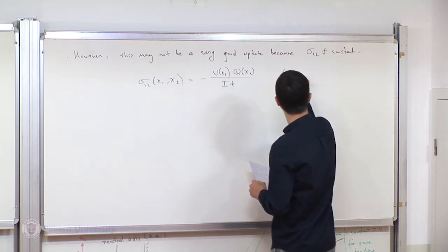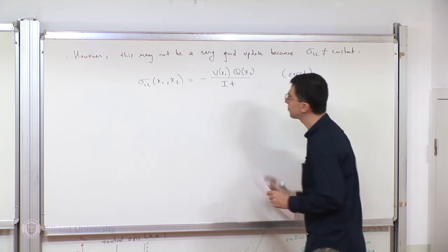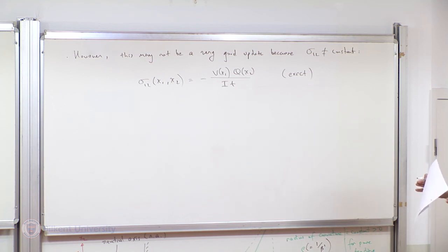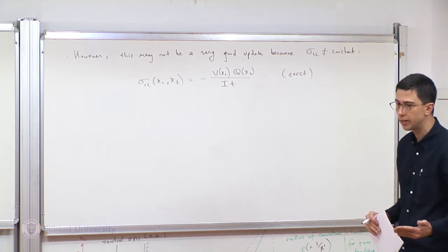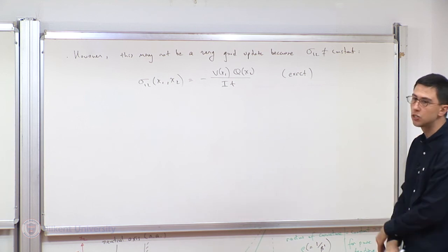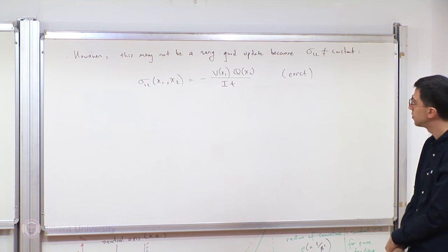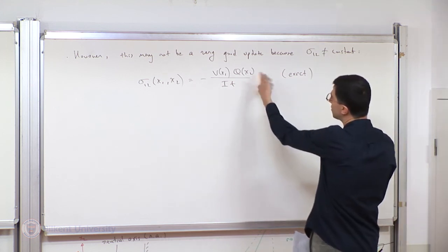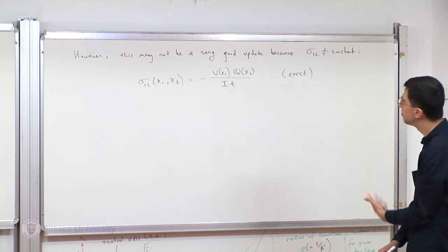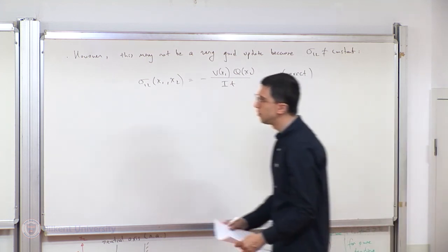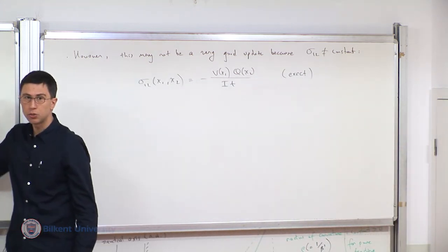Okay, so this is exact, right? But we are violating that. So even if plane sections were approximately planar, the shear stress is for sure varying irrespective of how slender the beam is. It's varying in some parabolic or nonlinear fashion because of the presence of that Q over there. So this if-then statement introduces an error.